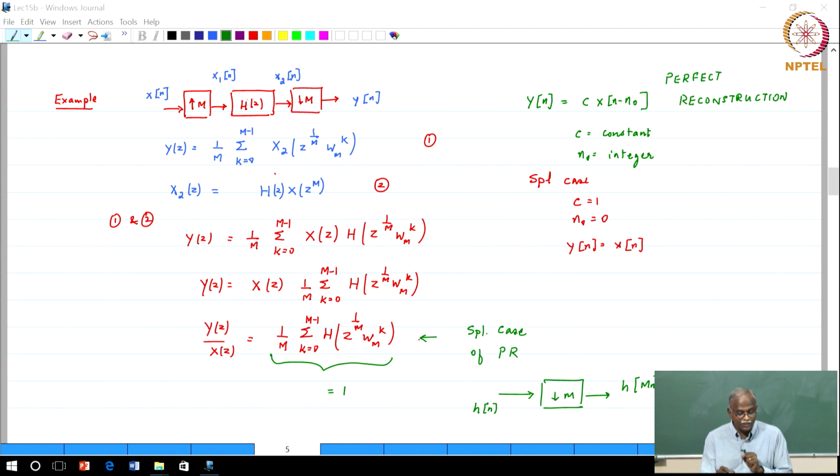Now, but this structure we have encountered previously. Where did we encounter it previously? Sampling rate change. Now, go back and let's reaffirm that whatever observation we have made is actually correct. Okay. Now, if I upsample by a factor of m and I want to do perfect interpolation, what would this filter be? Low pass filter, cutoff pi over m.